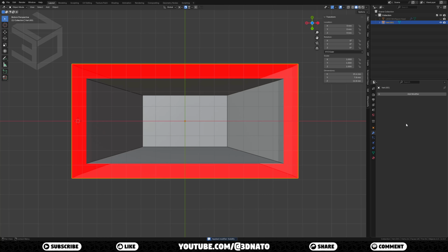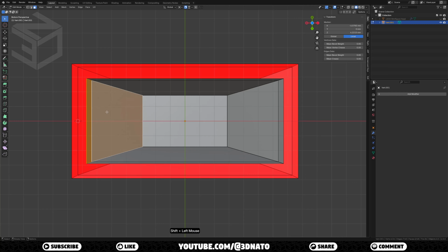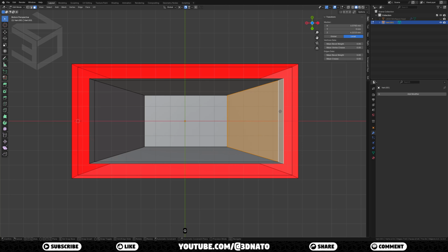As the thickness of the torso is not equal on all sides, let's move some faces. The left and right thickness is 1.2 mm, and the front and back is 1 mm. So we need to add 0.2 mm to these left and right faces. On Edit mode, select these two inner left faces, press G to grab, X to lock the axis, type 0.2, and enter to confirm. Now select these two inner right faces, press G to grab, X to lock the axis, type -0.2, and enter to confirm.